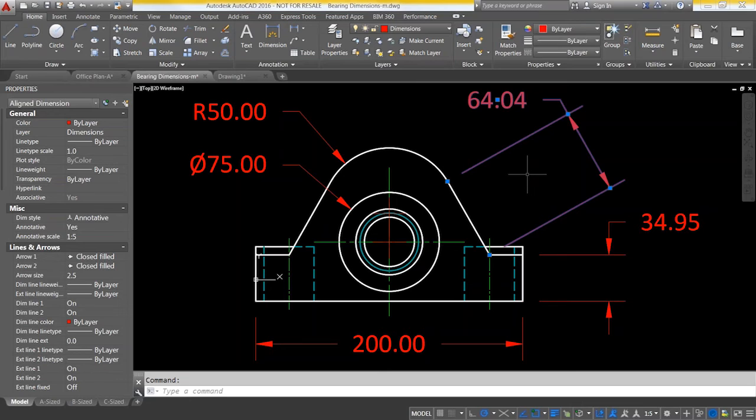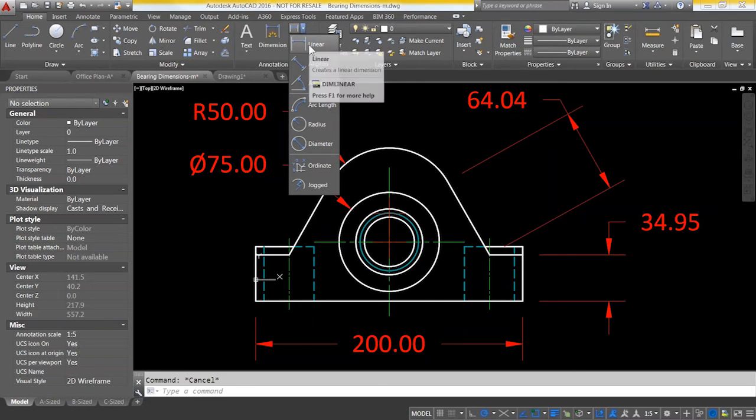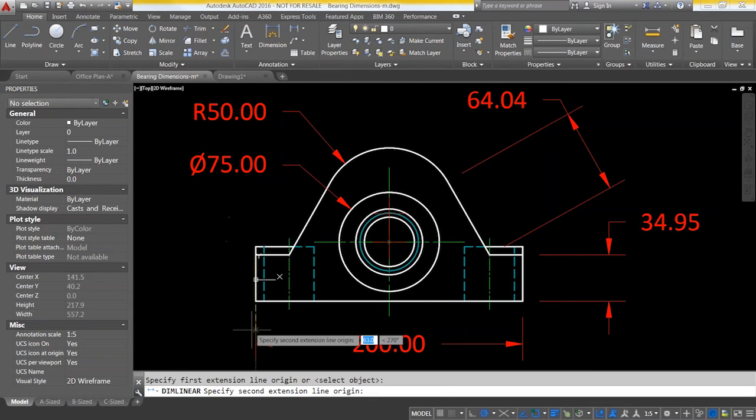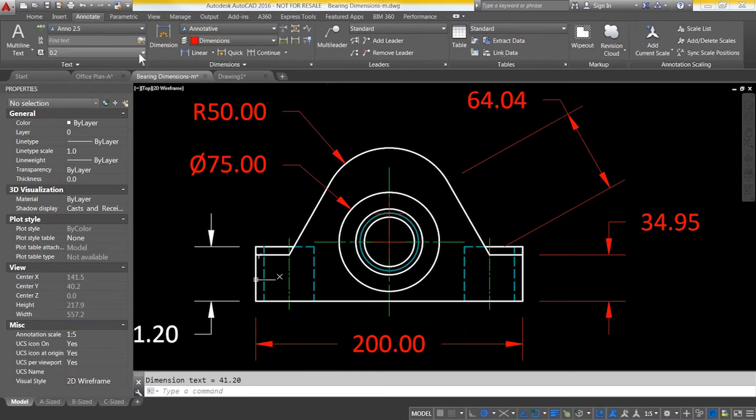They've introduced a new option in the dimensions. You can specify that when you're putting your dimensions in, they go on the dimension layer. Now, if I use a traditional dimension, such as this, that is actually on layer 0. So this only works with the new dimensioning tool. And to set it up, we'll go off to the Annotate ribbon, and we have the dimension panel right here. Use the drop down.